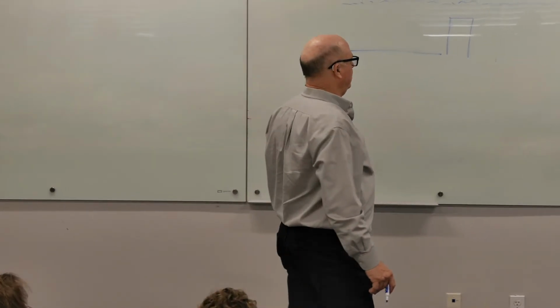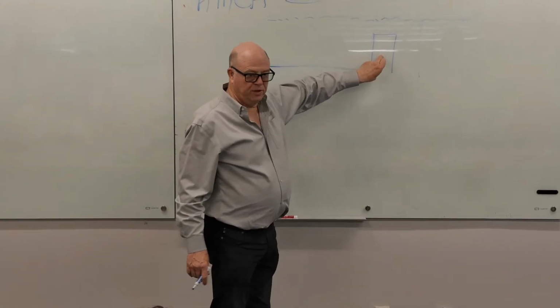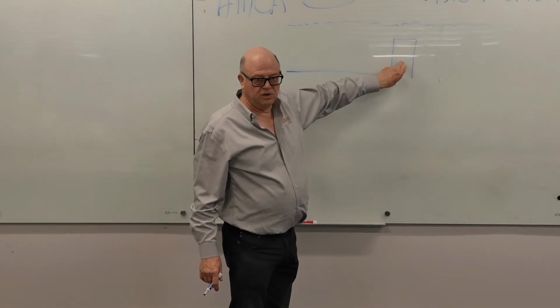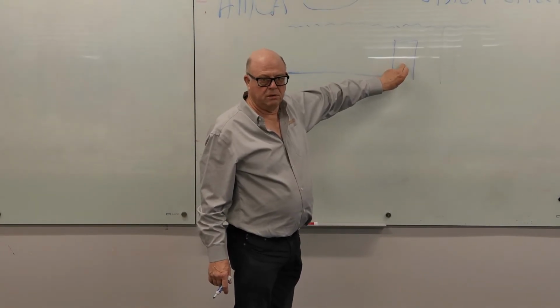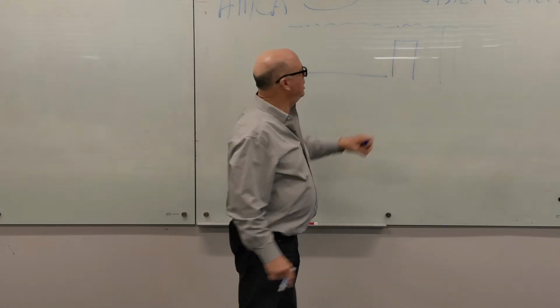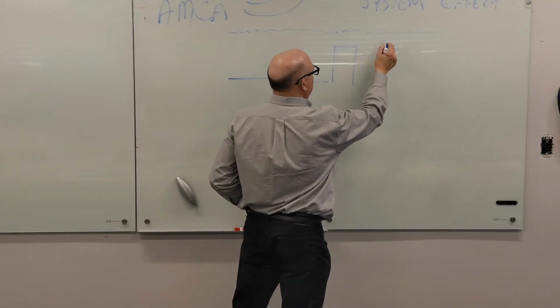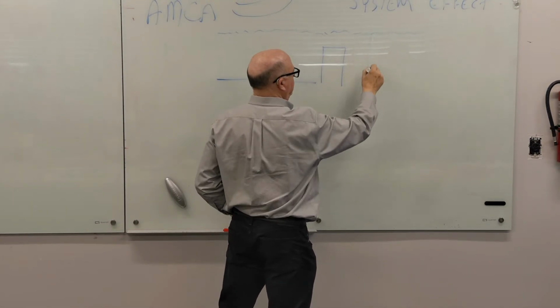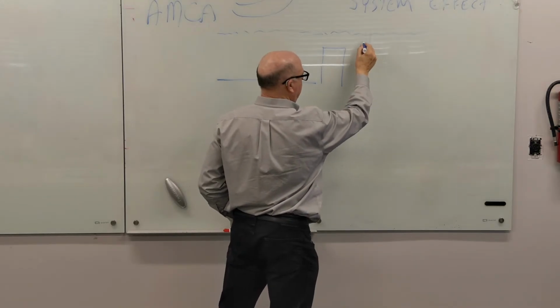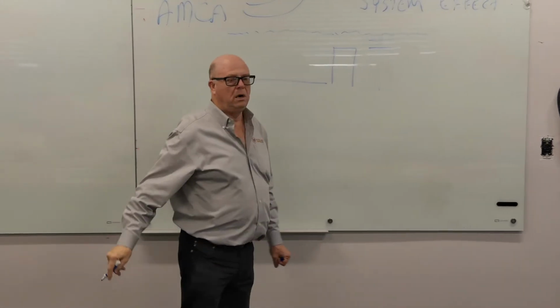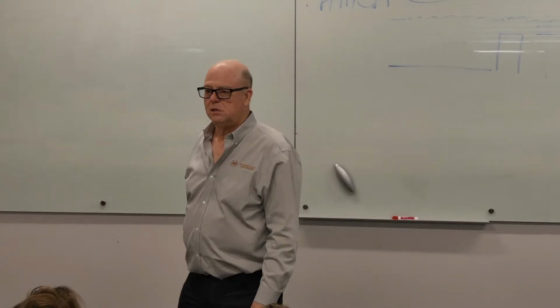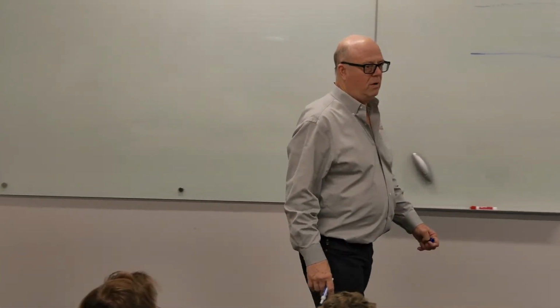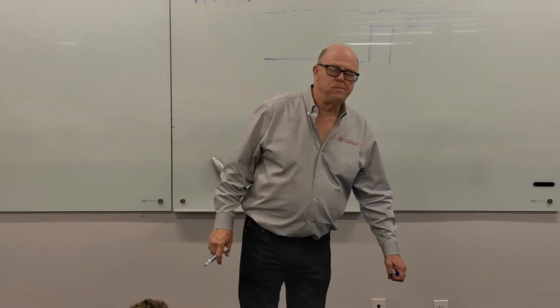What do you have to do if this hallway is a fire exit, an emergency exit, and it goes all the way to structure and a duct goes through it? Right. That helps. Combination fire and smoke dampers.